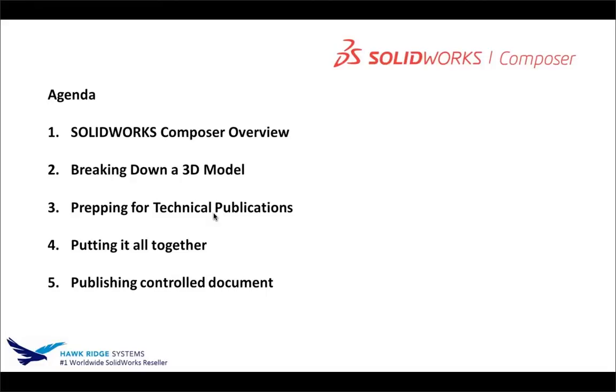And keep in mind we're going from CAD, which is SOLIDWORKS, into SOLIDWORKS Composer, which is defining all of the technical publications, and then we're exporting that as a PDF. That PDF is still associative all the way back to the original CAD model because we design it in CAD, bring it into Composer, publish the PDF. If it ever changes in CAD, change it there, go into Composer, tell it to change, and then just republish that PDF, and it streamlines and automates that process.